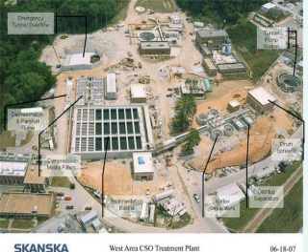At one of these screening facilities, the city has added what's called bending weirs. They are those metal things between the columns of the concrete there. They're installing these at this particular photograph, but they keep the water level up so that they maximize the flow through the screening systems and into the tunnel.